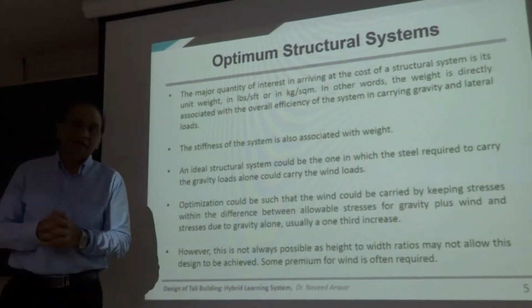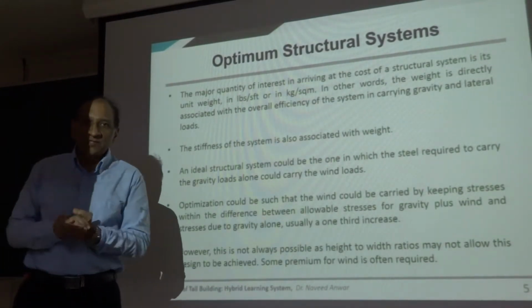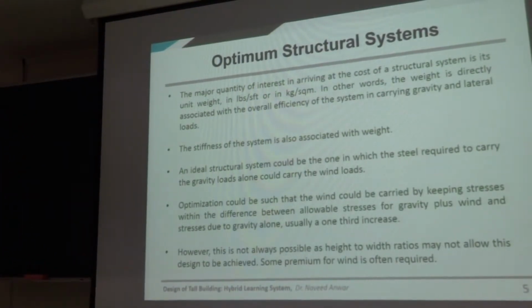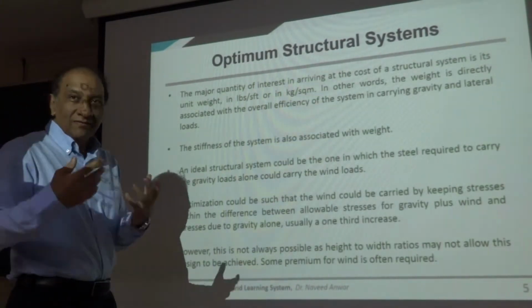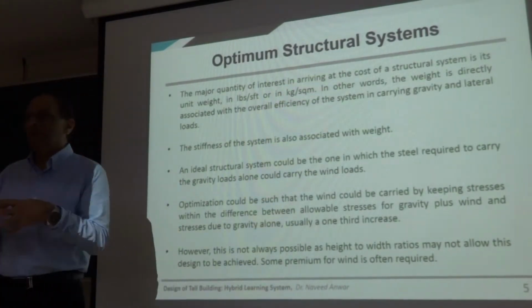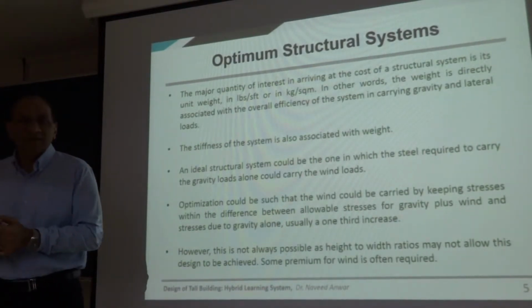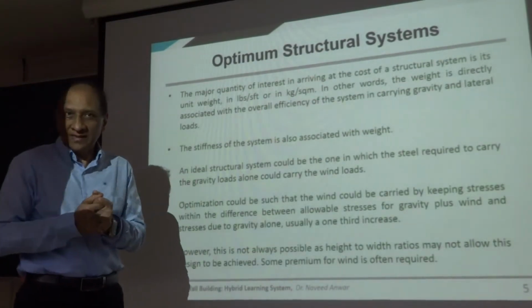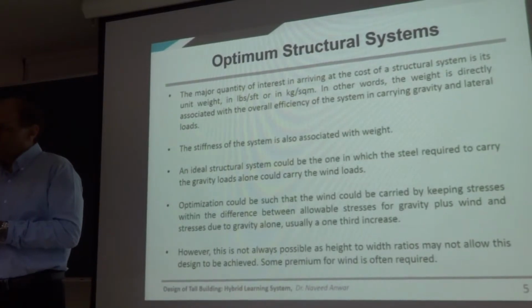Extremely efficient idea, right? And that's why when our friend was saying shear wall, shear wall, shear wall, I didn't want him to jump to shear wall, because shear wall adds things to the gravity load that we don't really need. So shear wall may not be the most economical, suitable, best option to go for a tall building, but often is the easiest one to use, right?